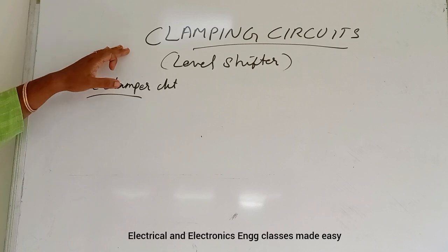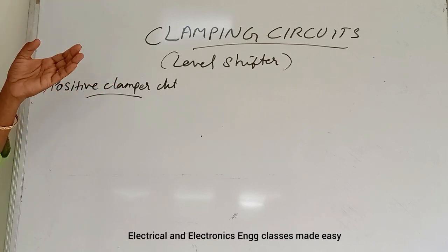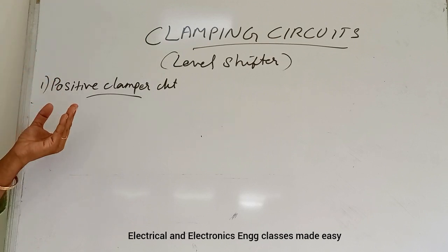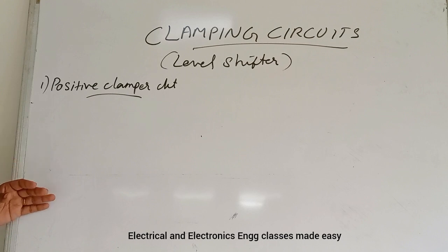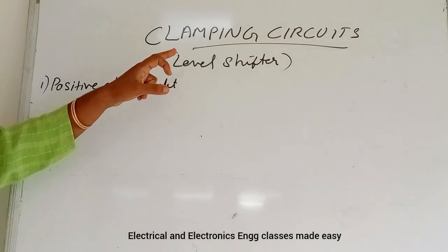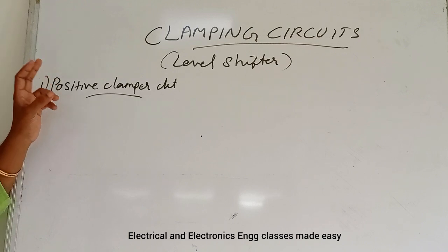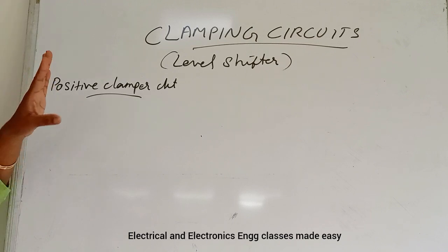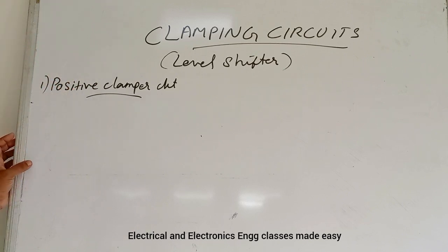A clamping circuit uses a capacitor, which is charged to a voltage and subsequently prevented from discharging, so it can serve as a suitable replacement for a DC source. This principle is utilized in clamping circuits, and the clamping level can be made at any voltage level by biasing the diode.